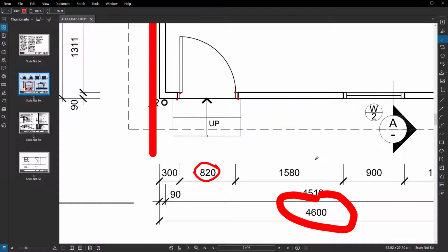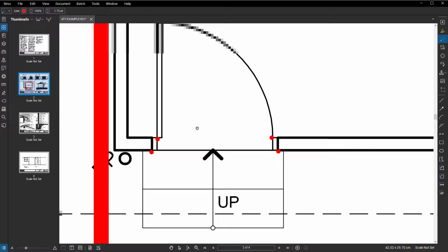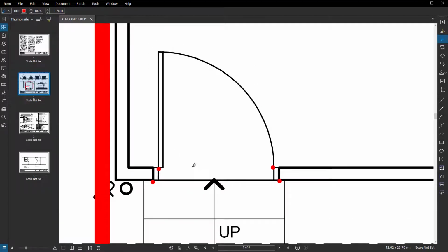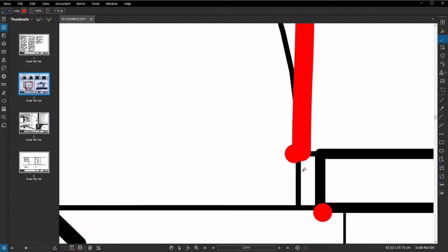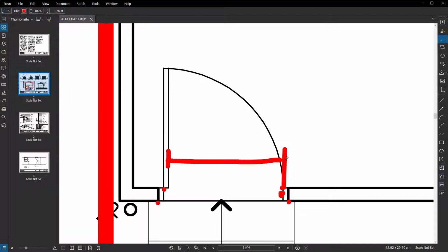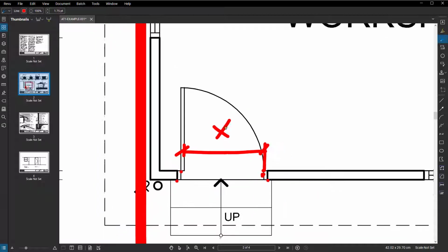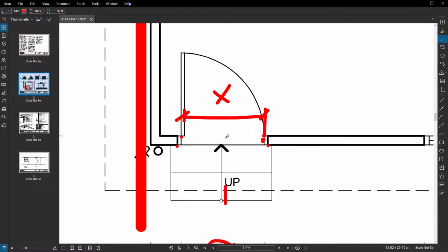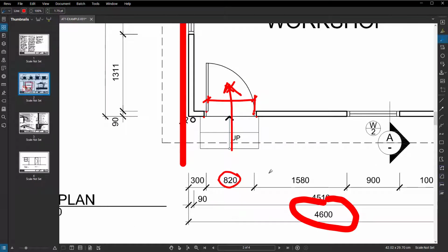and even between domestic construction and commercial construction. In commercial construction, sometimes they'll use what is known as the clear dimension, which is basically this dimension from in front of the door to just here. And sometimes they'll even include the little door jamb. The reason for that is because this distance here is fixed. So if you're in a wheelchair, you can't open this door any further to get through. So the clear dimension is what's really important in commercial construction, whereas in residential, it's usually the door leaf.